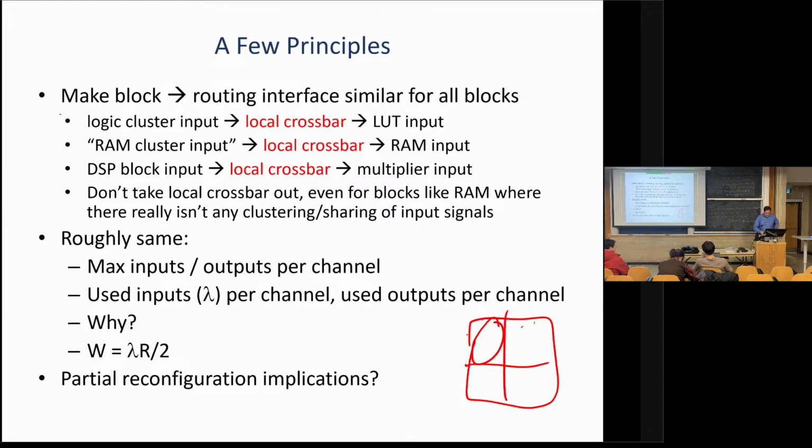So there are a bunch of academic works that essentially think of partial reconfig as virtual hardware. The idea being like you have virtual memory in your computer, so when you need something to be in memory, it gets swapped from disk into memory. Partial reconfig in theory could allow that to work, like paging in logic. So there are some academic works that try to investigate that. It's very hard to find an actual use case for it though, because the design flow is more difficult and the reconfiguration time is slower. So finding a case where that kind of fine-grained swapping of hardware actually results in a better system has been difficult.